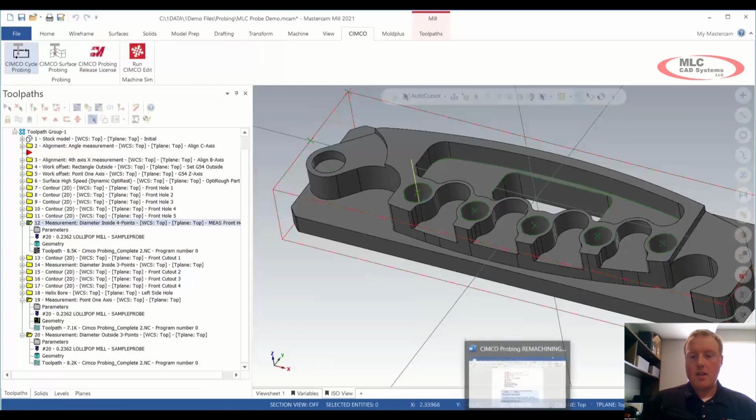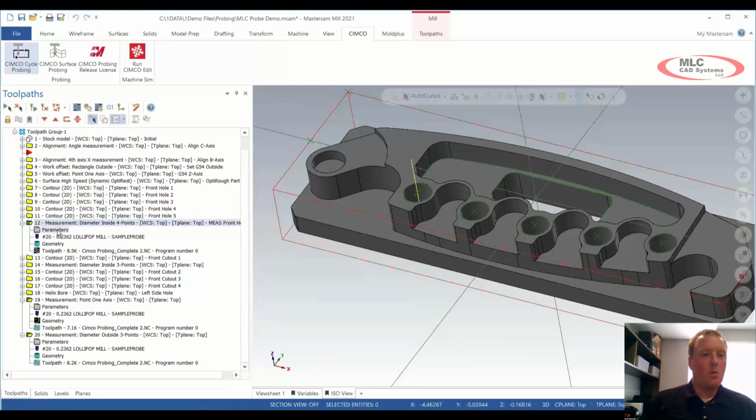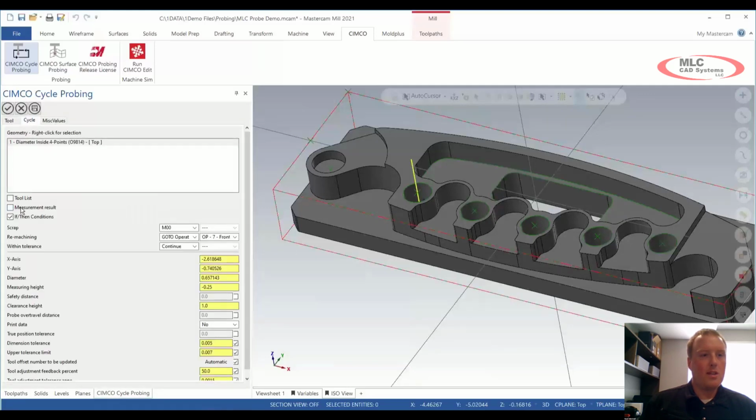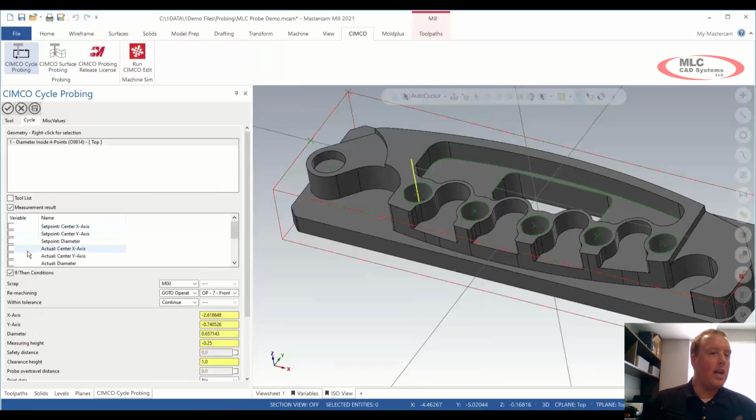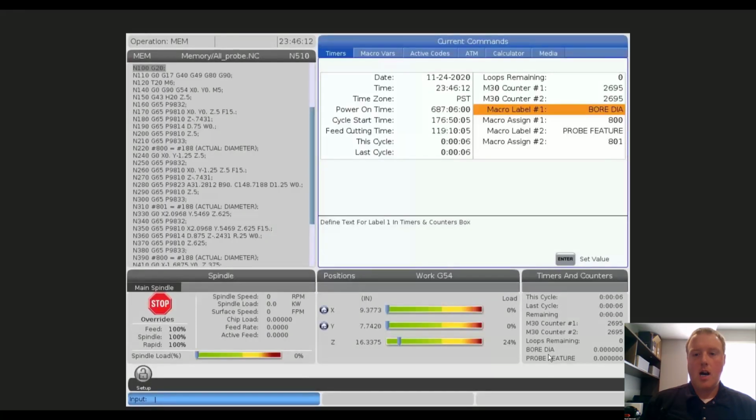I think that's all I had for the time being here. I was just looking through my notes. The one other thing I would mention is looping back quickly to variables. One option you could do, being that we're on a Haas machine, would be to set up your control where you can read off of a variable. This is a screenshot I just took, where we could label a location and tell it a macro number, and then on a control like this, it'll display that.